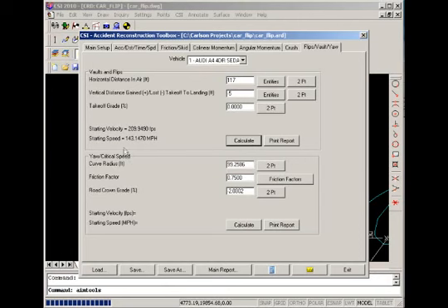So in order to carry a distance in the air of 117 feet, we had to have a starting speed of approximately 143 miles per hour. Down in the lower half of the dialog, we know that the car lost traction at 32.6 miles per hour. It began sliding, but takeoff speed on leaving the pavement was around 143 miles per hour.